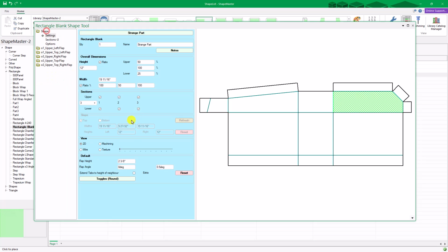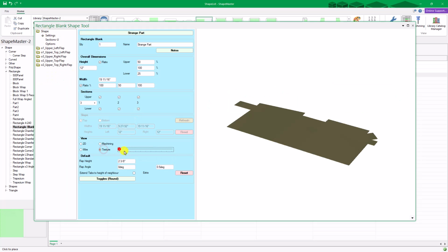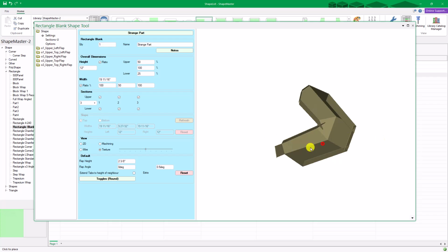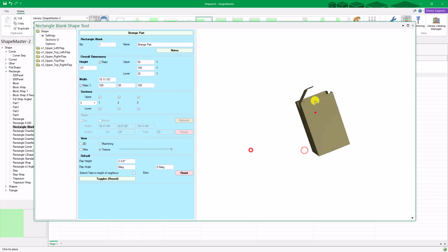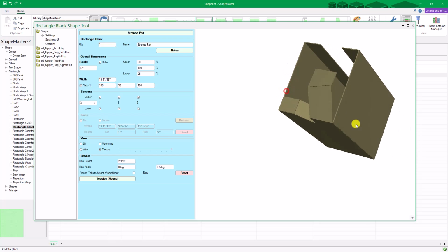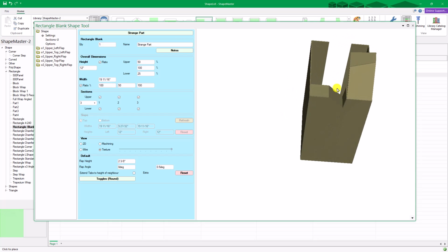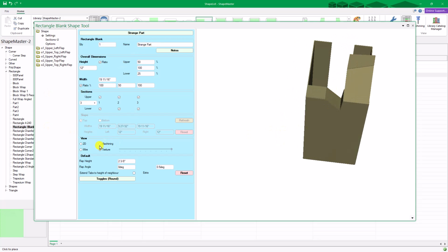And we can go back to here and textured, and then let's roll it up and see what it actually does. You'll see as it's starting to fold, it's a bit strange. It's not designed to be a proper part, but you see with the point, this one here now, you've got 45 here, 45 here, 45 here, so this one's now flat. So you do have a lot of control over how they fold, what angles they fold at, how you want to make it work. Again, once you're happy with that, F12 adds it to your list in the background.